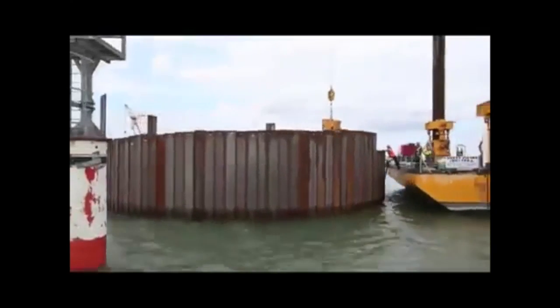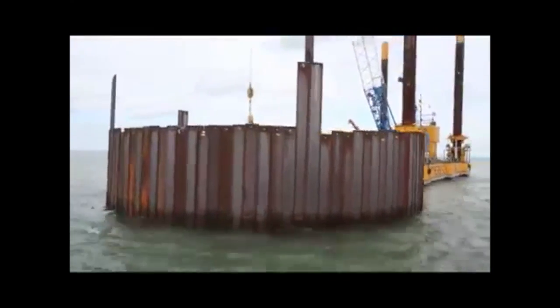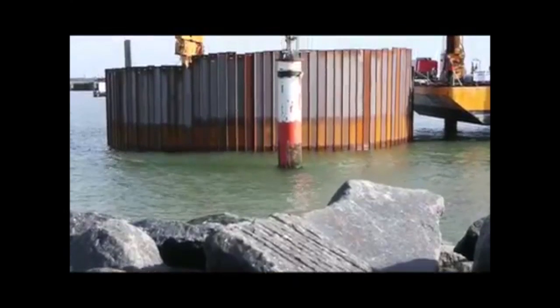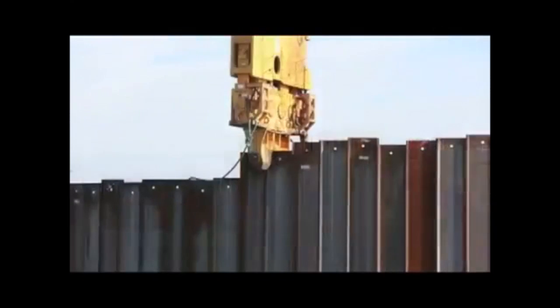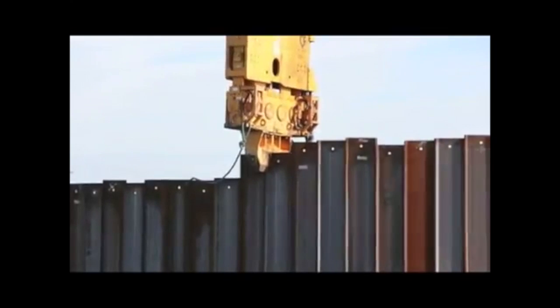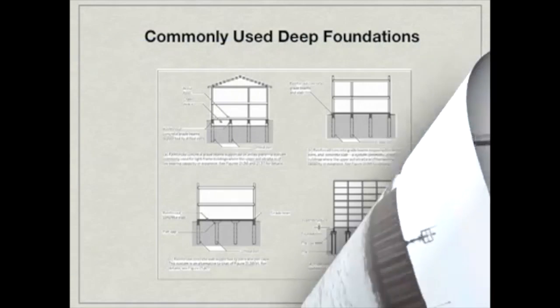Piles are generally driven into the ground by pile drivers, except concrete piles, which can be cast on site into pre-drilled holes. Site-cast piles, however, are typically called piers or caissons. So let's first discuss some commonly used deep foundations.